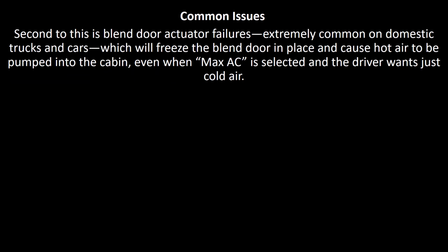They're extremely common on domestic trucks and cars, which will freeze the blend door in place and cause hot air to be pumped into the cabin, even when max AC is selected and the driver wants only cold air.